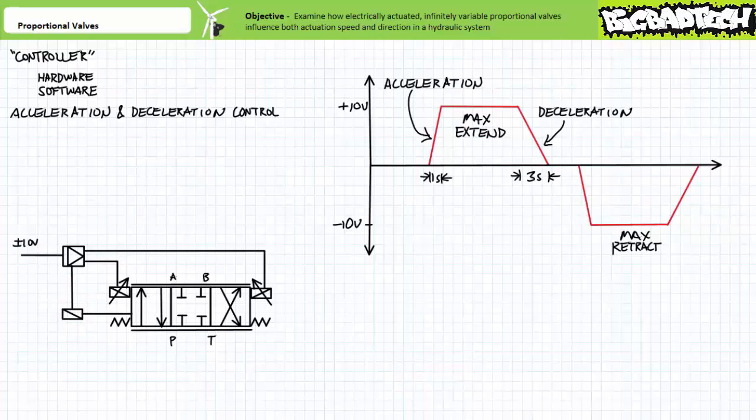Additionally, note that the position boxes of proportional valves sometimes have over and underbar lines to indicate that these are not mutually exclusive discrete positions, but rather infinitely variable. Additionally, proportional valve schematic symbols sometimes include flow control valve restrictions internal to the position boxes to make it explicitly clear that position influences flow rate. The onboard electronics may necessitate connection to a power supply, as well as a potentiometer used to adjust set points. These additional connections may or may not be explicitly illustrated on a schematic.